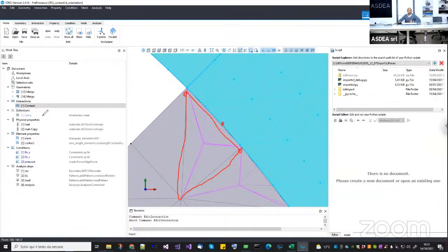But when I choose this option, so node-to-element, what I do is that I take the nearest element, I project the node using the outward normal direction of the edge. I project the node here onto this element. I create an auxiliary node. This node will be connected to these other two nodes, okay, using the embedded condition. Okay, so basically this node will move exactly on this edge.